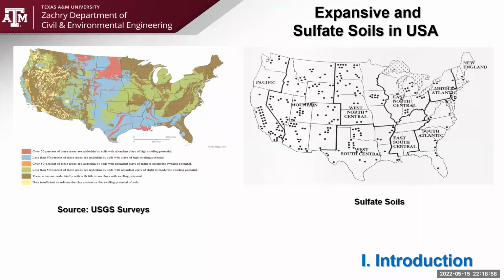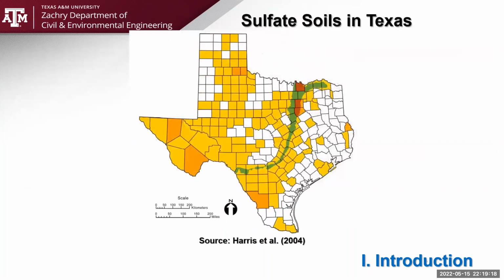So most of the time, expansive soils are stabilized with lime and cement. Those stabilizers actually react with the gypsum and form ettringite, which makes the heaving worse, because the gypsum and lime reaction leads to ettringite, which I'll show you how it works, and causes much more heaving.